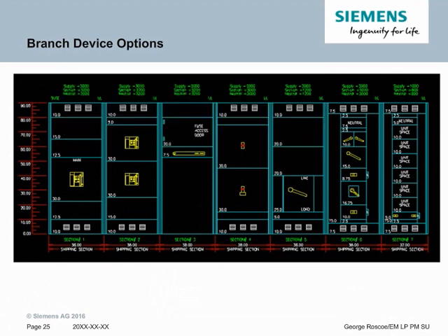Multi-case circuit breakers are typically horizontally group mounted up to 1200 amps. We can dual mount up to 400 amps, which is a Siemens advantage because we can mount 400 amps in under 30 inches of unit space.